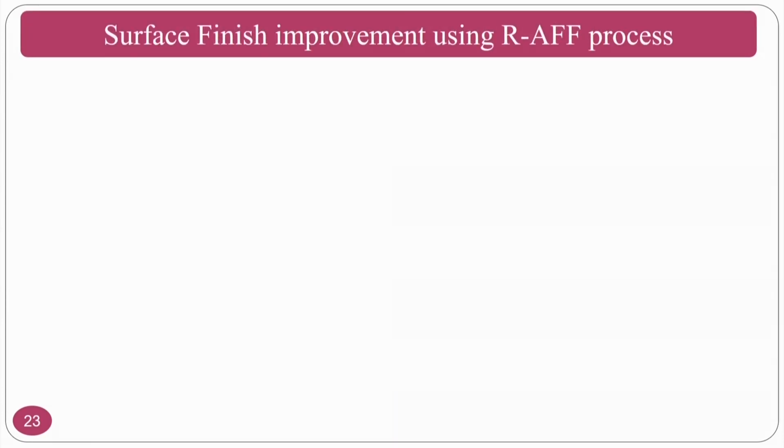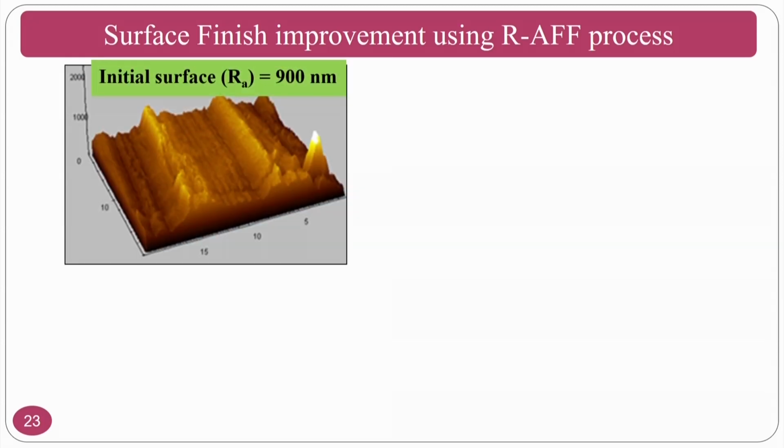So, surface improvement also we have observed in this particular process compared to the abrasive flow finishing process. This is the atomic force microscope image of the initial surface, that is, the workpiece prepared by the grinding process, and you can see the surface peaks.